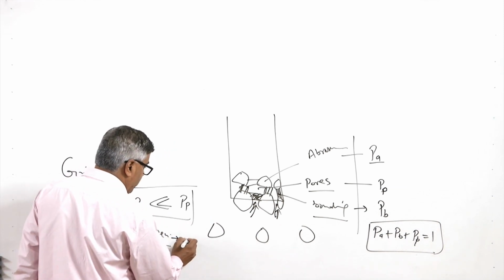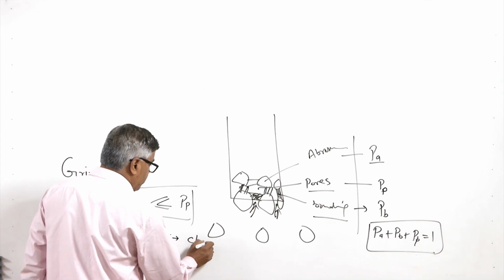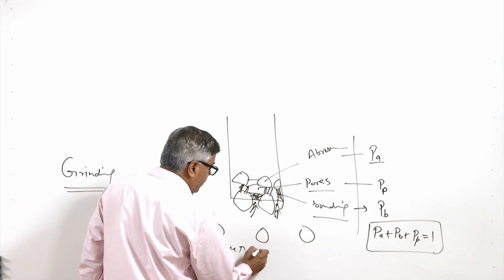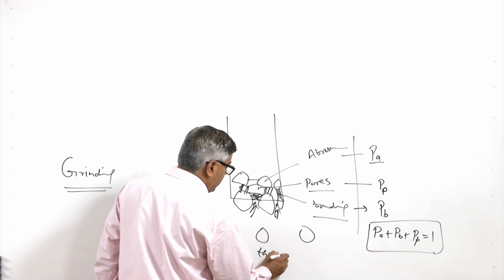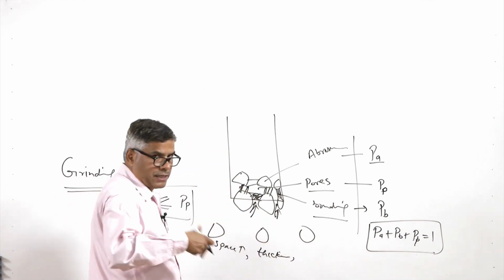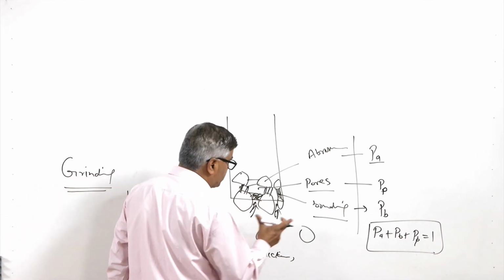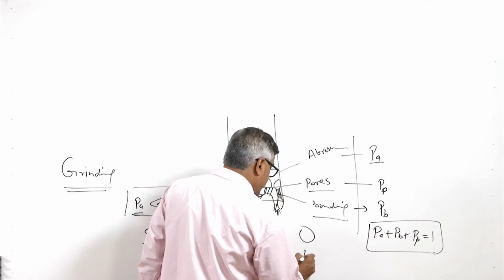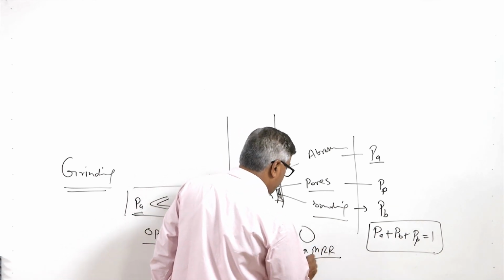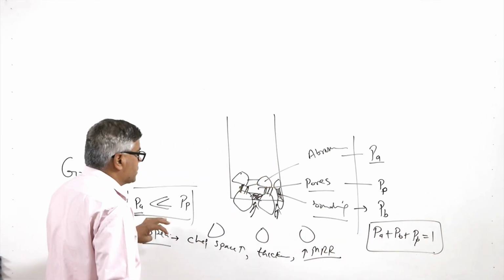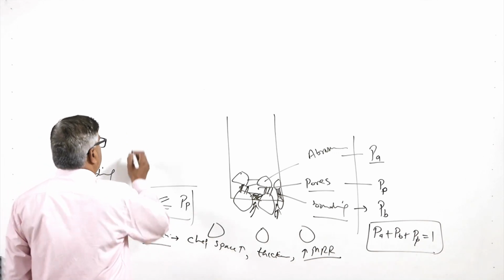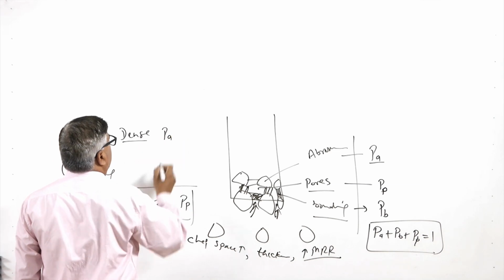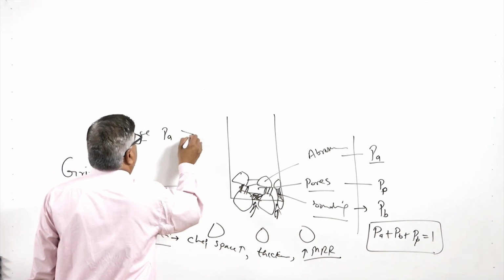So, when the structure is open, the chip space is more, which makes it suitable for removal of a thicker layer. A greater thickness of chip can be removed by the coarse abrasives when the chip space is more, and so this will lead to higher MRR. So, when higher MRR is required, open structure is used, while the dense or closed structure is used when the abrasives are more